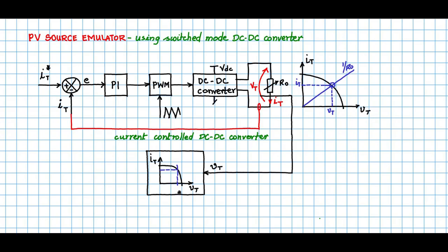So you see that in the lookup table, VT is provided as the input. It will check the independent axis and appropriately pick off the current IT to be given out. So this IT is given out and fed to the reference. So this way the setting for the IT reference is done.